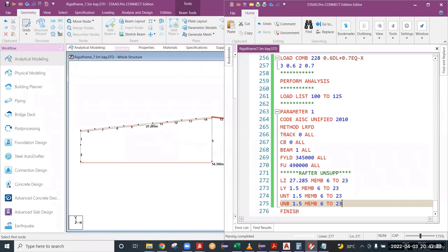Okay, from the purlin. If the purlin is running like this, you can drop one flange brace. A flange brace does not need any design. You can provide some angle, like 50 by 4 or 75 by 6, anything. You can provide one angle to the bottom flange. That is how you can take unsupported lengths for the rafter.